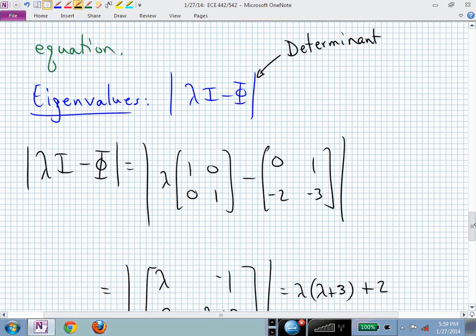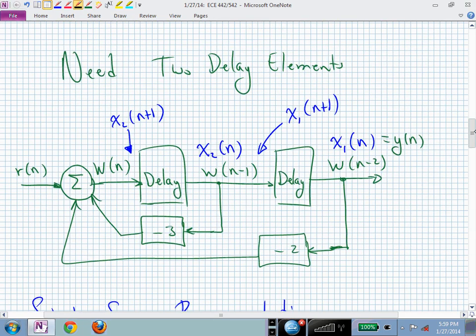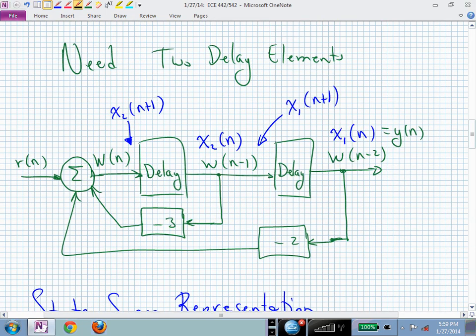This is why I said you might want to attend an art class, right? Now all you have to do is sketch. You just have to draw. You've got this all-delay block diagram. All I'm asking you to do is replace the delays, which are time domain operators, with a frequency domain operator, which is z to the minus 1. And everything else stays the same, except now all your signals are not indexed with n's, they're indexed with z's.